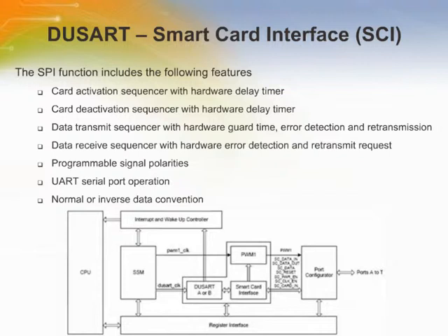It should be noted that while all of the necessary sequencing for card insertion, activation, and deactivation is in place, there is no built-in support for voltage level switching, tamper detection, or short circuit protection. It is therefore necessary that an external interface circuit is included between the chip and the Smart Card terminal itself.